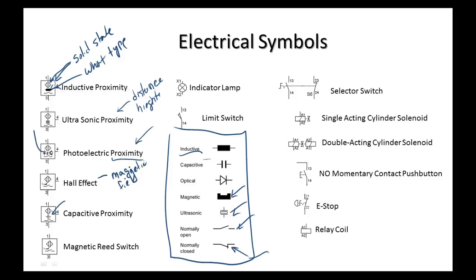Well, all those sensors that sense the position of these valves. We have two things that sense a magnetic field. Now notice we don't call this a proximity sensor. We call it a what? It's a reed switch. Yeah, I was looking at this one, sorry. This senses a magnetic field too. See the little symbol right there?